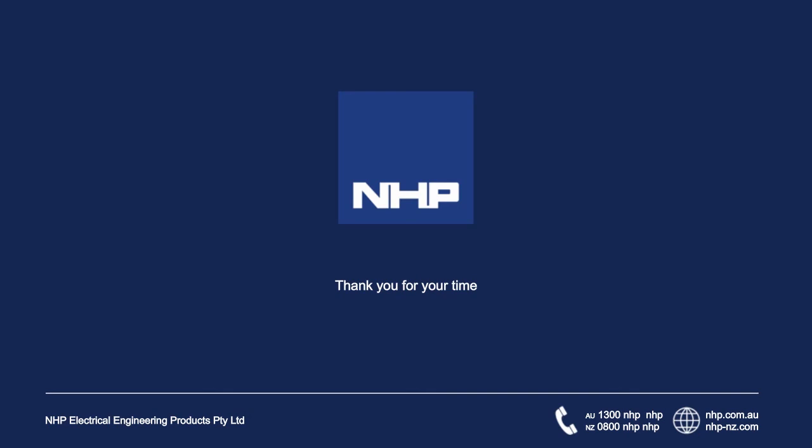Just in brief consultation there, Steve, with our product team, as this is a live webinar, I'm just discussing with one of our commercial engineers. When we look at 14 ACBs locked together in zone interlocking, we can make some assumptions that we can have reasonable lengths of cables, because it's not often we're going to see 14 ACBs within the same 10-metre space, shall we say.